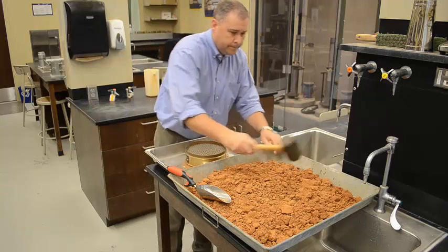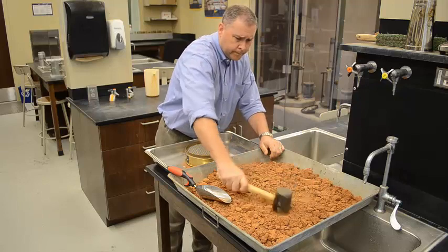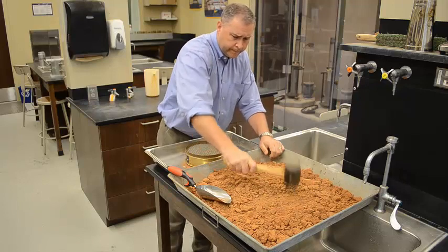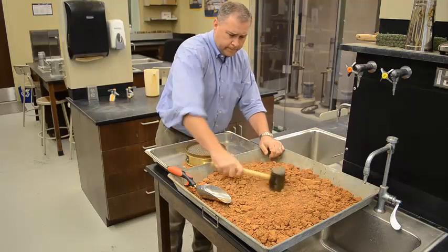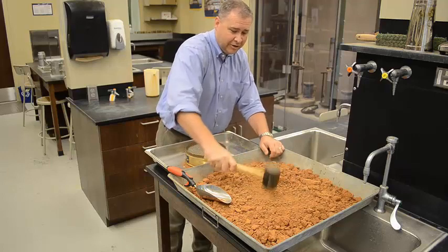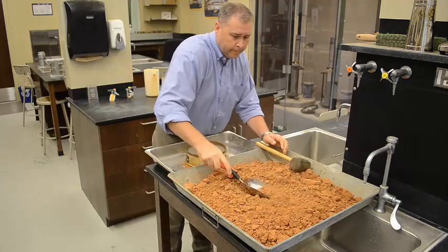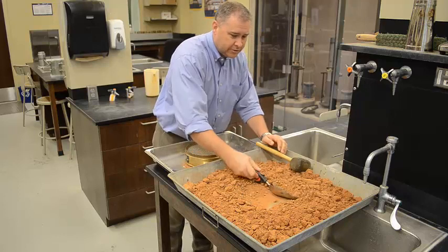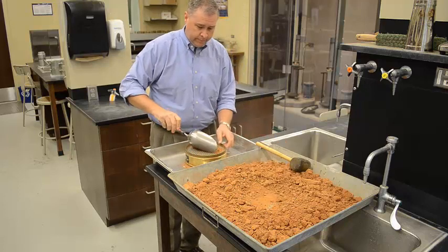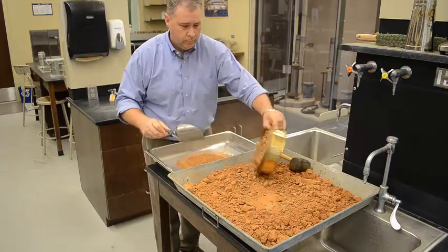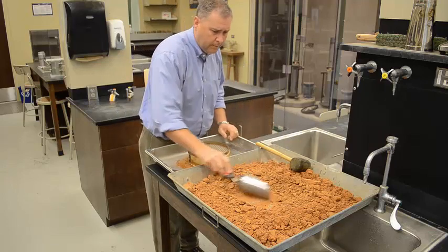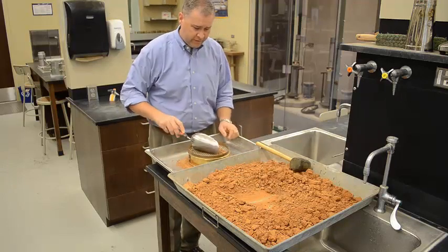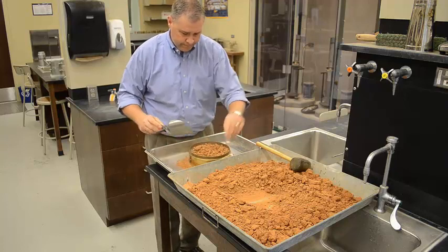And the material we have here can be easily broken apart. You can see the rubber mallet there breaking some of it apart. You can use the hammer from the Proctor hammer that you'll see a little bit later, or you can use the rubber mallet. I'll have all of that available to you. And you want to collect enough sample that you have about 7 pounds, 7.5 pounds total of -4 material. Okay.